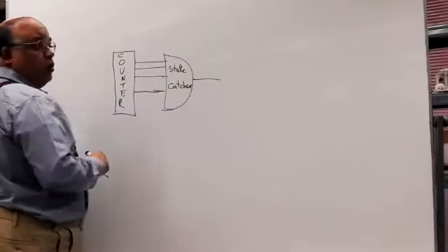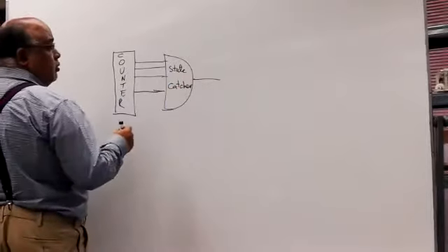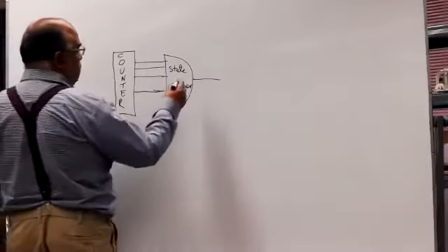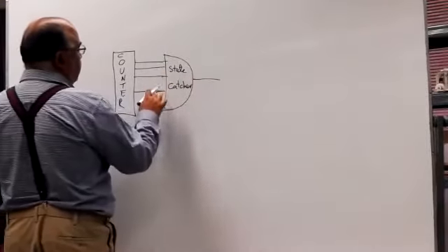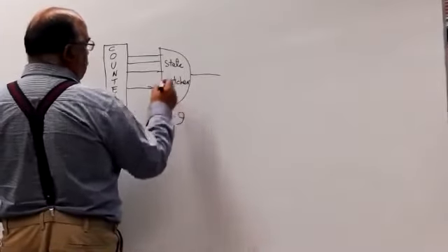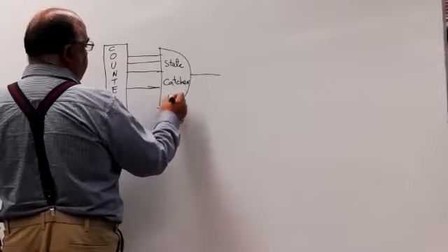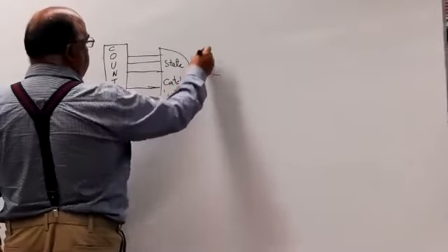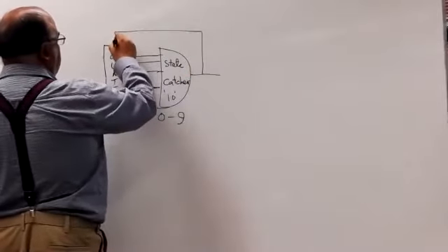So this state catcher, zoom in a little, sir. This state catcher, when a certain state is reached, for example, when we made 0 to 9, we made this state catcher for 10. And this would reset this counter.